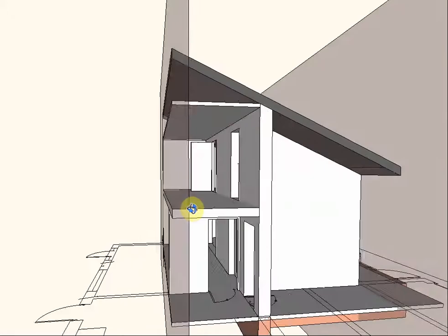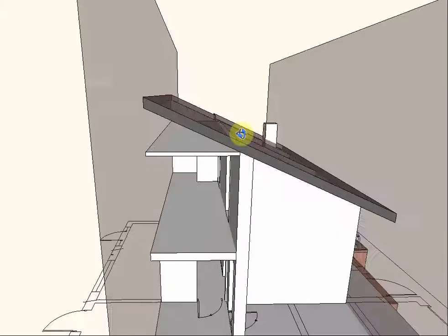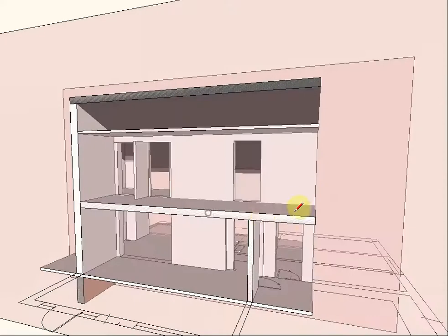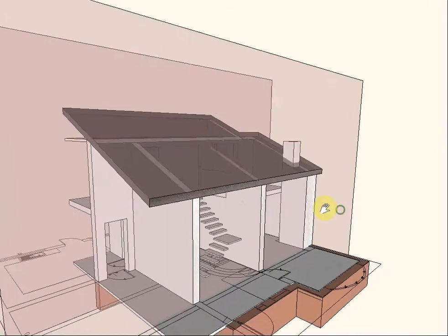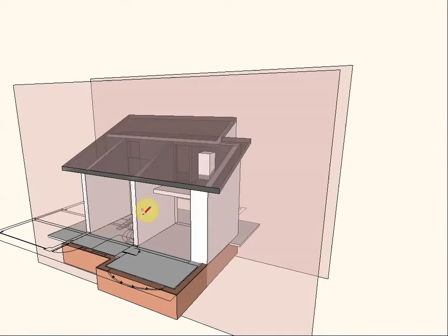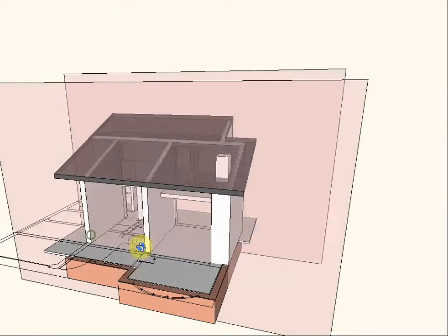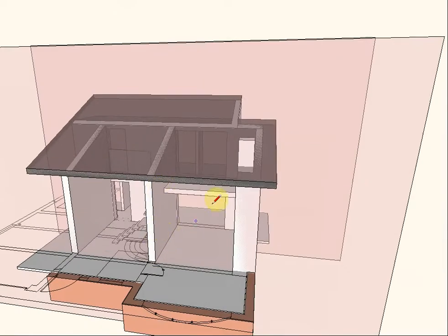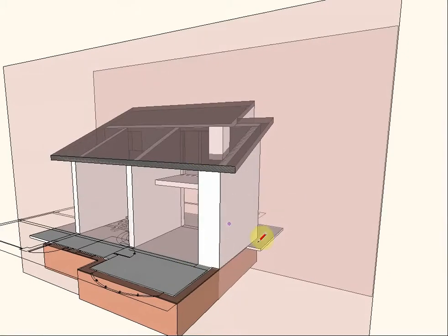existing building. This middle spine wall here is the key thing, with openings punched through it at the moment, and then the sloping roof is supported off these intermediate walls that divide the property into three. These are all staying, all these structural elements will be staying, although partially demolished. The end gable is going to be completely demolished.